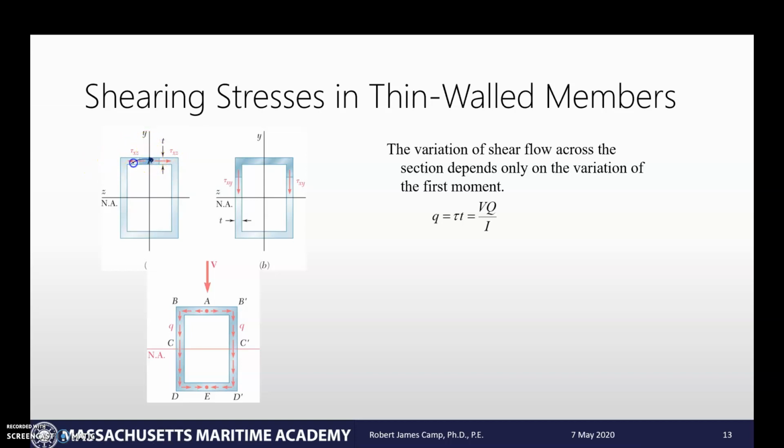And it's going to go from here, and it's just going to flow all the way until it meets back at the bottom. It's just going to go down there just like water would, and it's going to vary through there. And you can calculate what that shear stress is at any point by taking your cut, and there's my area. This would be my A prime, and I find out what Y bar prime is, and I can calculate all that just like I've done with the other problems.